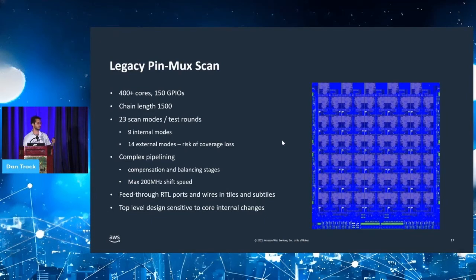And of course, everything must be tested. So you need to make sure that every such small interface is covered, and that you do control all the active wrappers on this interface together, and it's covered by one of your pin max configurations. So this process is both time-consuming, and also there is a risk here of missing out on something and eventually end up with coverage loss, okay?